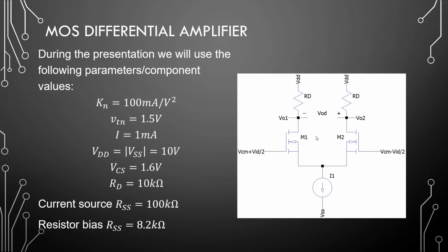Okay, so first off, here on the right hand side we have a nice MOSFET based differential amplifier, and the assumption is always that the MOSFETs and the resistors are matched. It's driven by a current source. This current source can also just be a resistor, but we will get to the negative effects of having a resistor here a bit later.